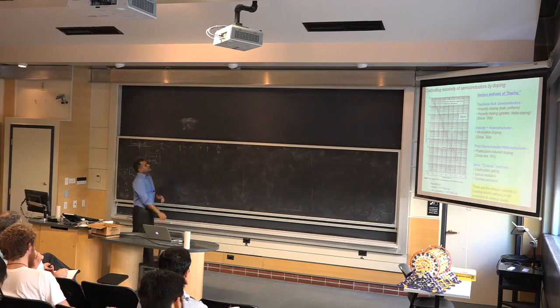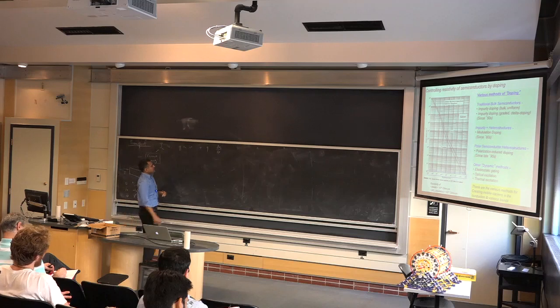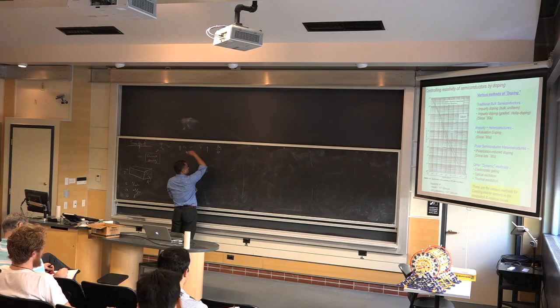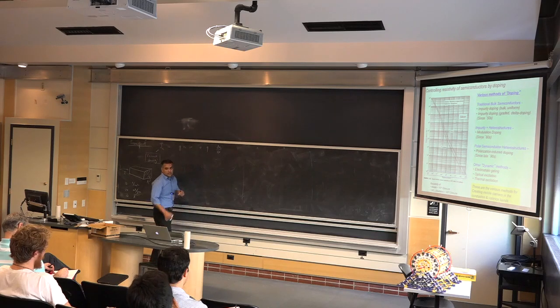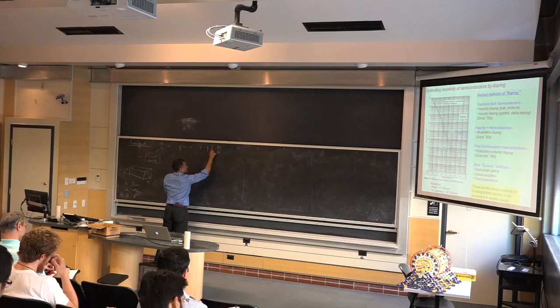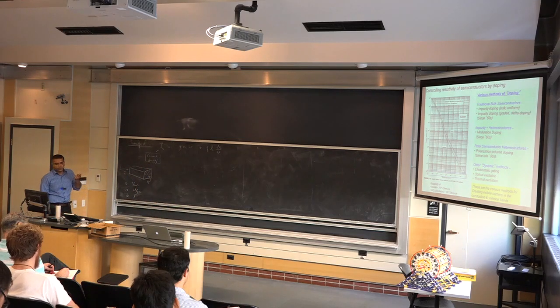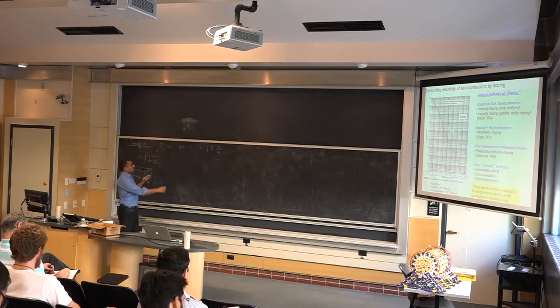This already shows you that there's some sort of diffusion going on. Electrons are flowing from larger density regions to smaller density regions. And there's a coefficient that represents how easy that process is, which is called the diffusion coefficient. So that's drift